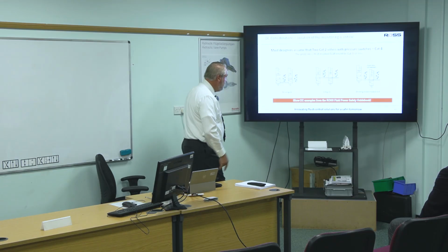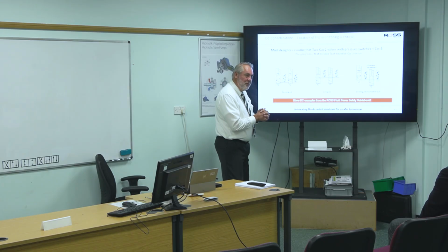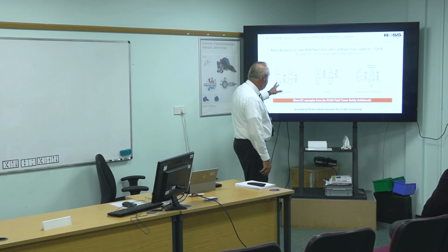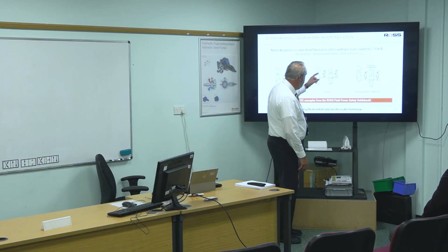So I've had people do this and say, I'm going to use 2 valves and I'm going to use 2 pressure switches. And I said, okay, well, you're not going to get to high diagnostics. Here's why. When the valves are off, the pressure switches say they're off. When the valves are on, air is being supplied, both pressure switches are on.